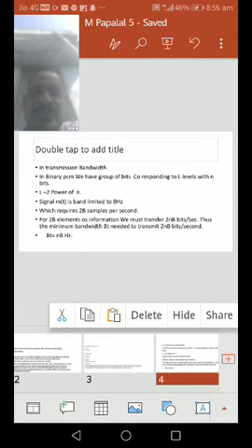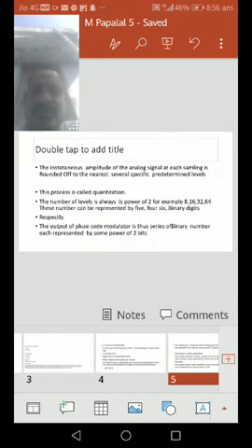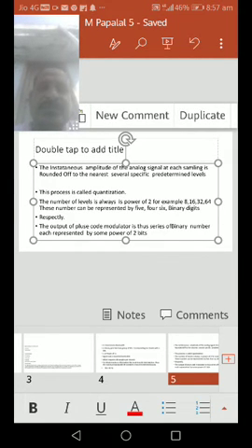Then after that we have sampling. The next stage goes to the quantized levels. We have the number of quantized levels. If it is n bit data, 2 to the power of n, so 8 bits gives 256 levels. If it is 2 bits, 2 to the power of 2 is 4 levels.